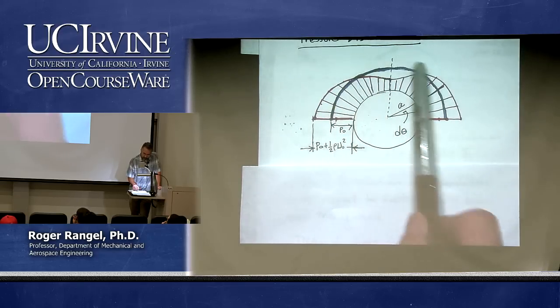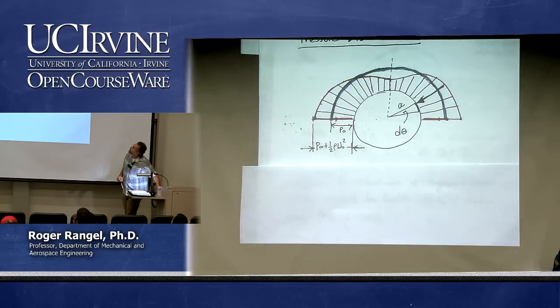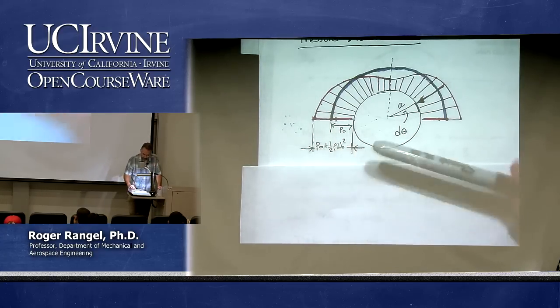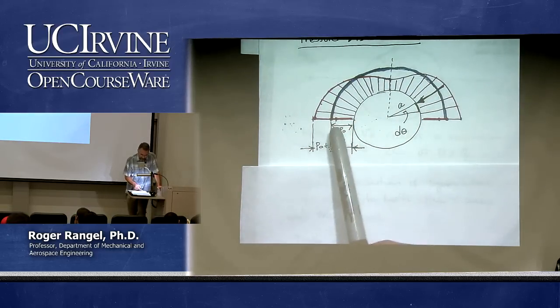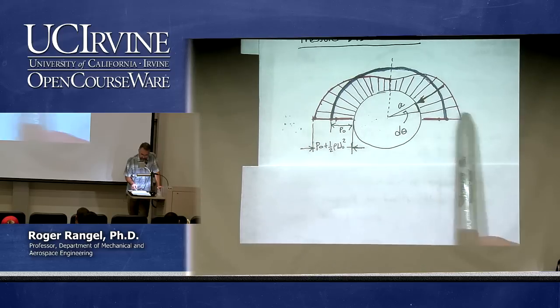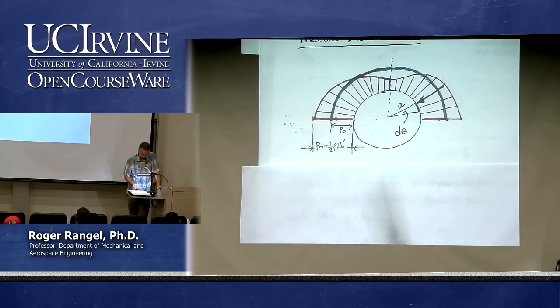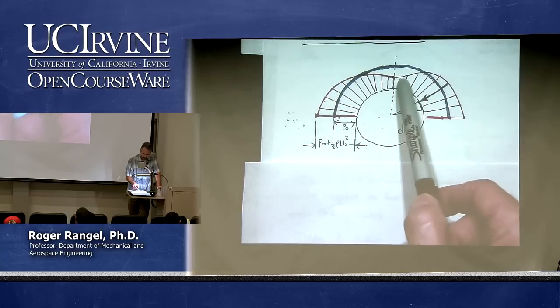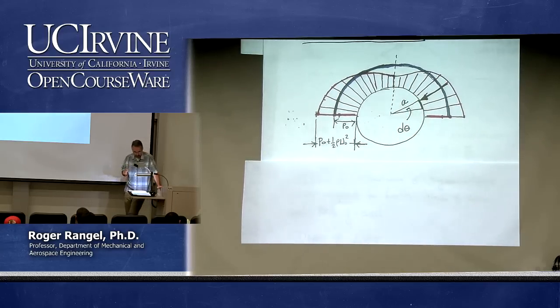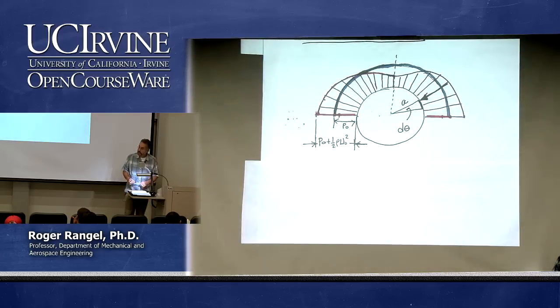The blue line that I put here, which is a semicircle, represents what? The static pressure of the free stream, right? That's P naught. P naught is the same all around, of course. I put it there just for comparison, so that we can see that the pressure at the stagnation points is higher than the atmospheric pressure, the pressure ahead. And in fact, the pressure drops under. That's what we were just talking about. It's the minus 3/2 as it drops on the top. And this is symmetric also with respect to the x-axis.